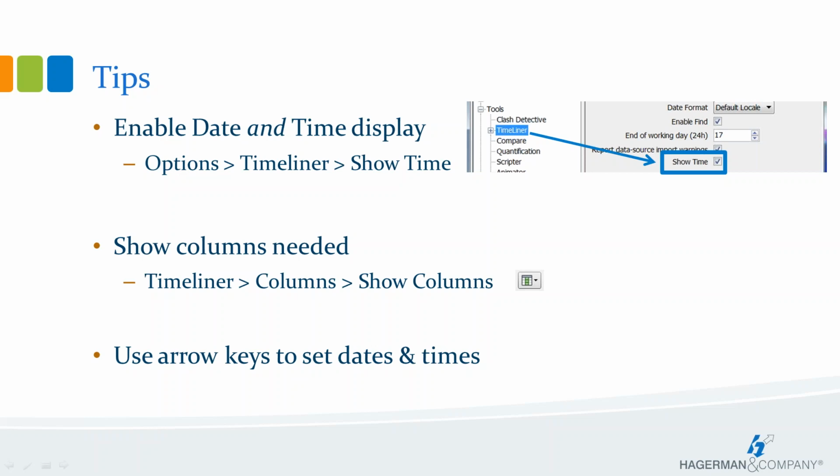Lastly, use the arrow keys when setting and adjusting the dates and times versus just keying them in. Occasionally, Navisworks will play tricks on you in this area. You may try to enter a different date or time, hit the enter key, and you'll see that your change did not take. That can happen, but if you use the arrow keys, for some reason, it always works. So keep that in mind. They just seem to be more reliable.